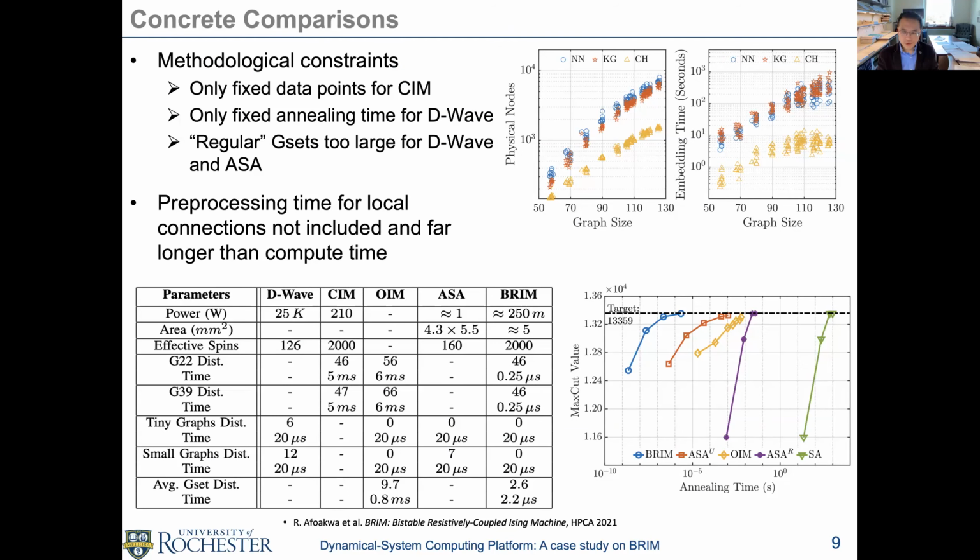Yes. So the room temperature is for sure, and that's part of why we think some non-ideality, what's called PVT, process voltage and temperature variation, may come back to haunt us to some degree, although during the high temperature phase of the annealing, we're actively injecting noise, so we're not too worried about that. We believe this chip of 2000 nodes will burn sub-watt, so the energy efficiency should be good.